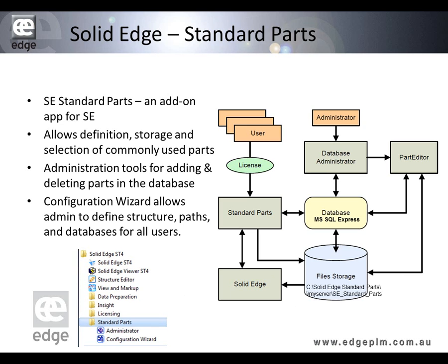We put a master file for each category, and the database, as we call up individual, let's say we're calling up a bolt of a certain type, an ISO bolt of a certain classification, and we call up a certain size, it will actually build the Solid Edge part file from the primitive using information in the SQL database to make that on the fly. Once we've built that and we call that up again, it will be called up a lot faster. You'll see this in action as we're going through.